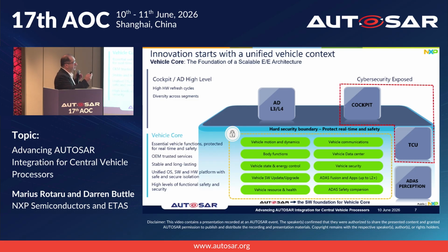We talk here about services that provide body functionalities, vehicle communication, vehicle dynamics, vehicle health management, etc. This vehicle core is not just the hardware. It's a unified OS software together with the hardware platform, together with safe and secure isolation. We consider that the vehicle core, together with the AUTOSAR OS, creates a foundation of scalable vehicle electronic architectures.